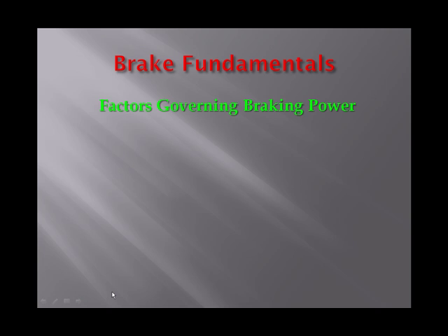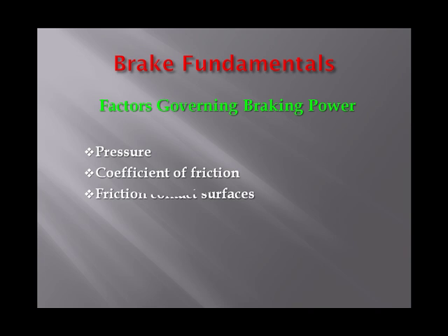Factors governing braking power. There are four basic factors that determine braking power of the system. The first three factors governing the generation of friction are pressure, the coefficient of friction, and the friction contact surfaces. The fourth is a result of friction, and that is heat.